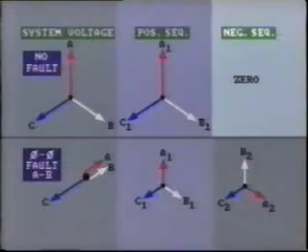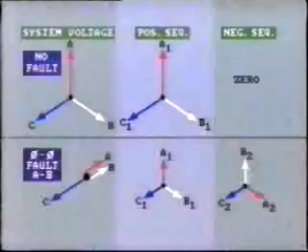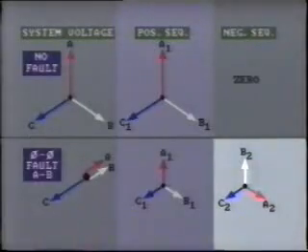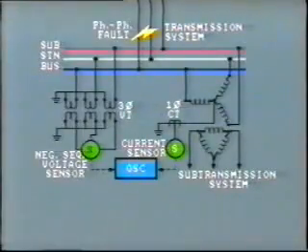The negative sequence component is zero. As soon as the fault is applied between A and B phases, the negative sequence voltage suddenly increases. So when this sensor detects negative sequence voltage, we can be quite sure that a fault has occurred and recording can begin.